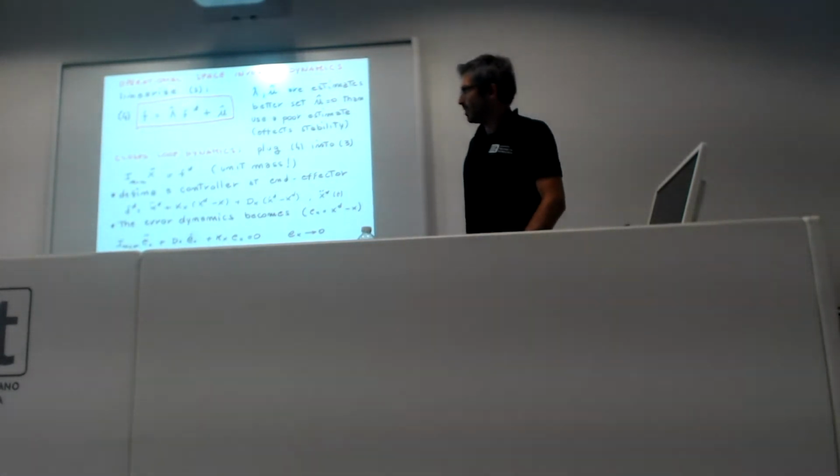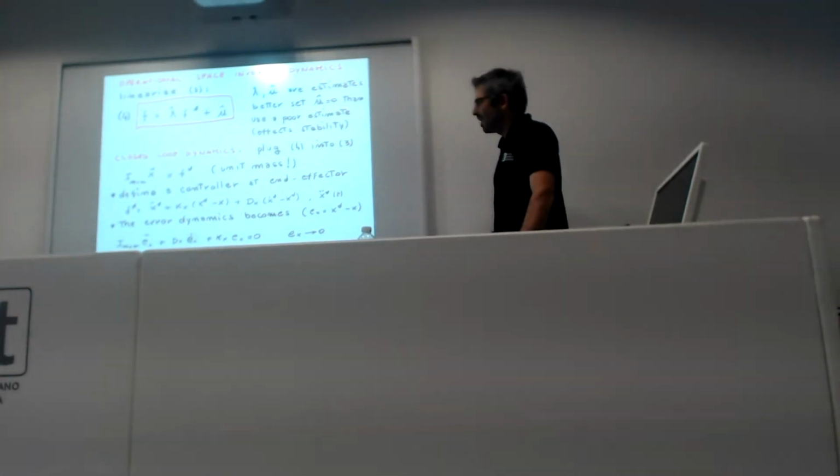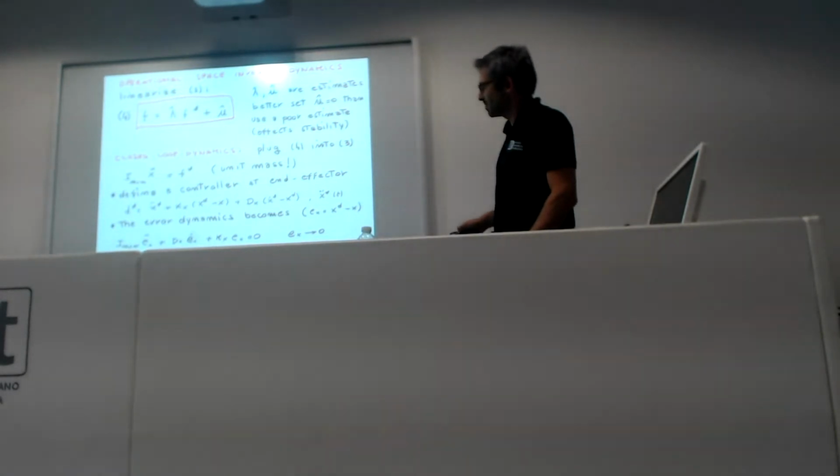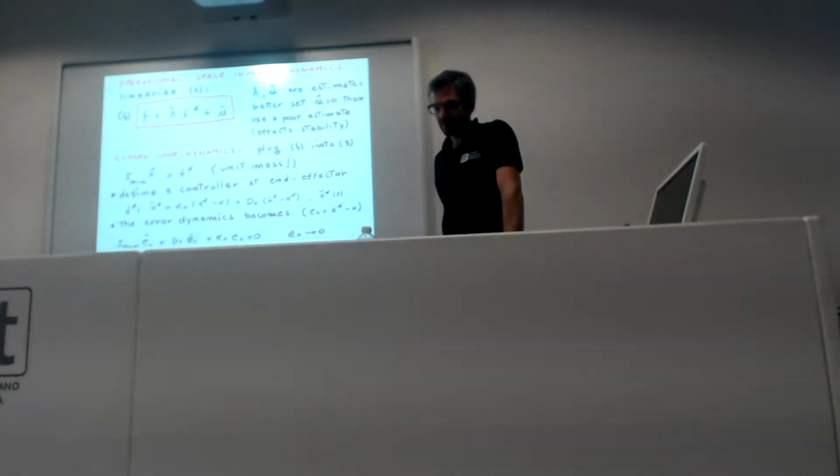And how do we get the torques? Because this is the last point, right? The last point is to do Jacobian transpose F in essence, and we get the torque to send to the effectors.